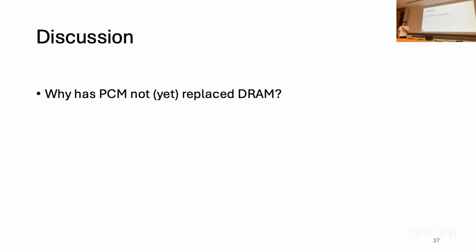Well, I would assume that it's probably mainly due to the limited endurance. As you said, in this paper, they kind of assume they have perfect wear leveling. But if you want to have any kind of wear leveling like they do for flash memory cells in an SSD, that adds a whole layer of tons of extra latency, which probably would make it then far less competitive with DRAM. Yes, that definitely is one of the reasons, I'd say. I did not list it here as I did not think of it. Any others?